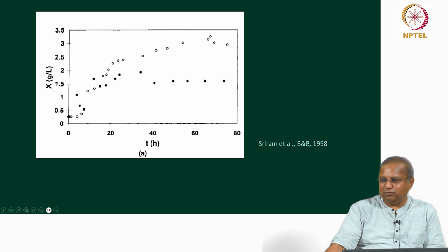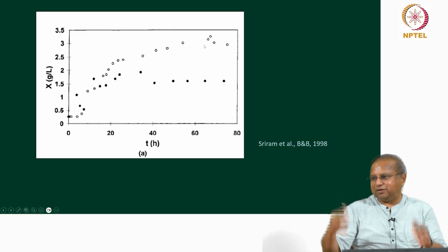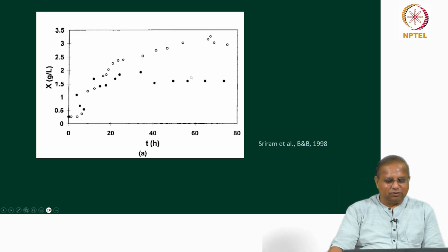This leads to a reduction in the maximum cell concentration as well as the growth rate. Growth rate to a certain extent, definitely in the maximum cell concentration. This is with aeration. This is with LPOS. It's about half. Okay. So I got greedy as any engineer would. So I said, if I can increase this to here, then the productivity goes that much more. So how do I go about doing this? The reason for the reduction seems to be reactive oxygen species. So how do we handle the reactive oxygen species so that while using LPOS, the cell productivity also becomes high?